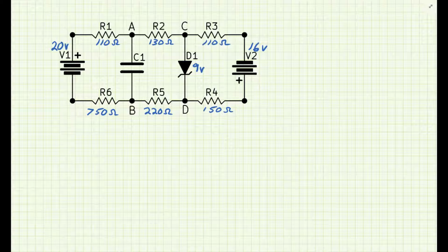So it's a DC circuit. There's nothing about the capacitance given, so there wouldn't be any way to do any time constant or charge analysis on that capacitor. So I really have no choice but to assume that it has a full charge. I'll just imagine this circuit's just been running and I walked up and looked in and saw this circuit. So we'll consider that capacitor to be a full charge, which means to DC,